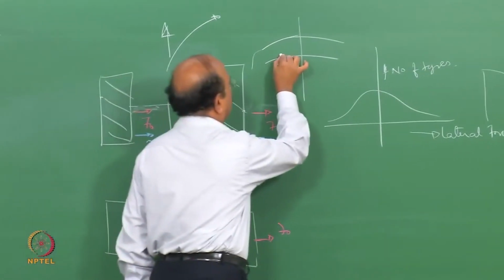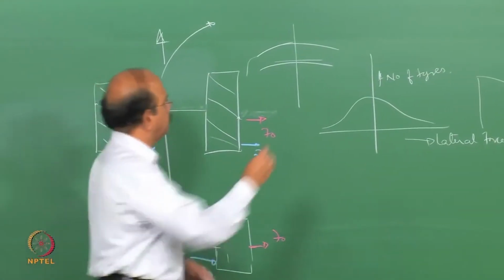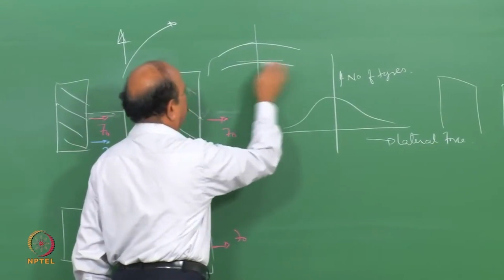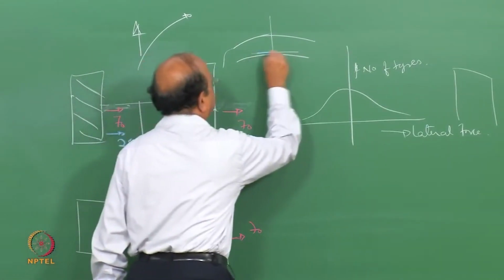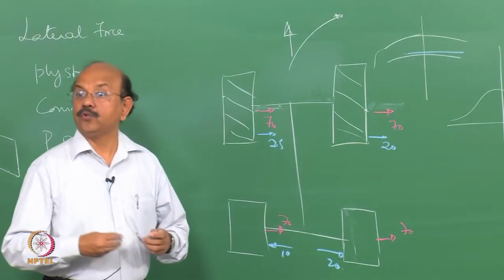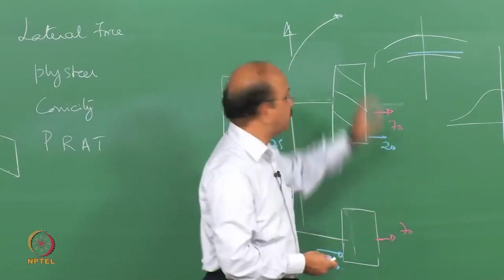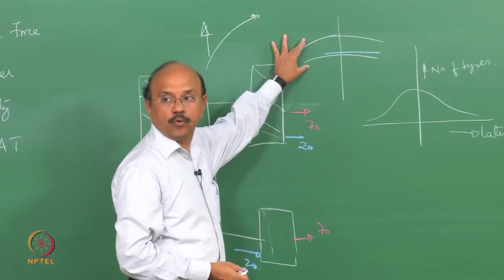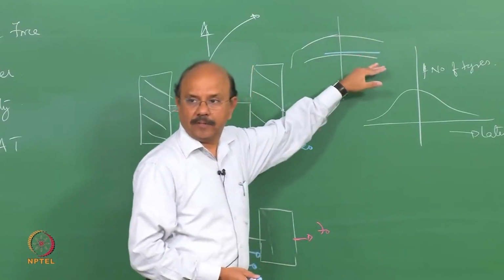So I have a distribution of the belt, and if the belt is offset, instead of being symmetric about the center, if the belt happens to be something like this, offset in one direction, we saw those belts the other day, then due to inflation pressure, this side would go up more than this side, which is stiffer because of that belt offset.